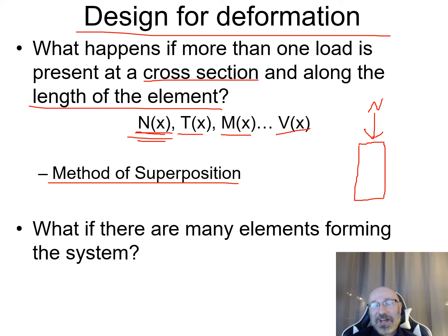But in reality, let's say it's kind of like I drew it. It's not perfectly straight, because this is a great example of me trying to draw this with my mouse. Same type of thing if I'm trying to actually machine and make this. Is it perfectly straight? Or maybe there is a slight angle to this, and then all of a sudden this load is not a purely axial load, and there is a bending moment as well on this. Or maybe somebody comes and pushes it from the side because it's going to be used outside of its intentional use.